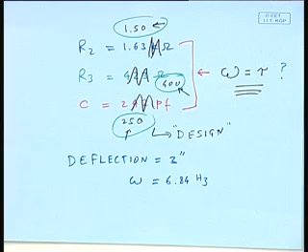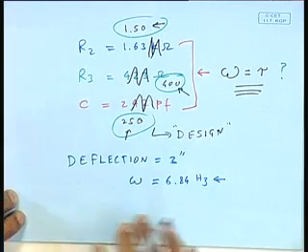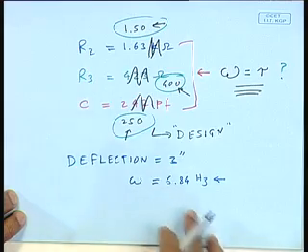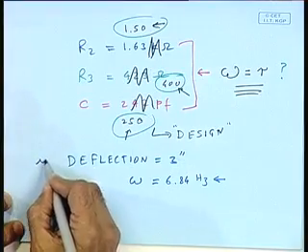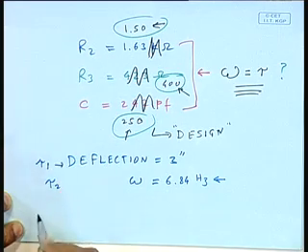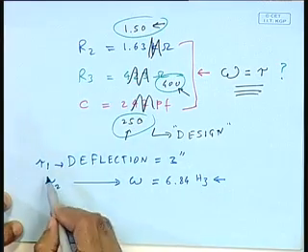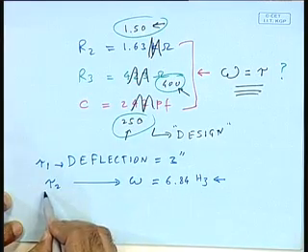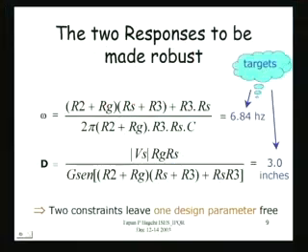That, you can see, is a pretty low sort of thing, and this is generally the kind of vibration that you get when there are people moving around and so on. You'll get vibrations like this. And this 3 inches is the full deflection of the galvanometer. These are the two targets that we got. So you've got tau 1 here and you've got tau 2 here. I've got to make sure, as Taguchi said, I get this performance on target, tau 1, and this performance also on target, tau 2. And we've got to make sure the whole system is robust. Let's see how we go about doing this.